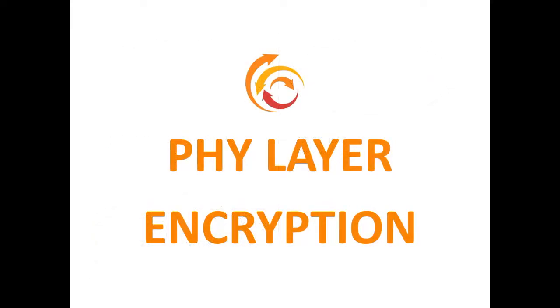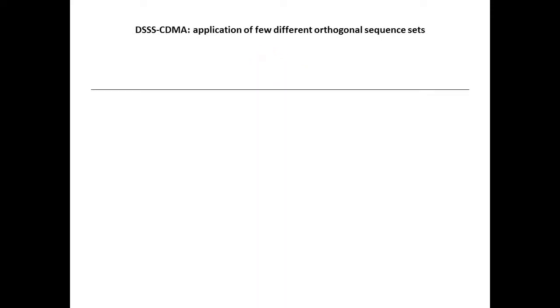The company's physical layer encryption technique belongs to the first type and is based on the direct sequence spread spectrum CDMA technique. Common DSSS CDMA uses Walsh, Gold, and Kasami codes for data transmission. Also, other modern complementary, zero correlation zone, or large area synchronous codes are considered for use in future CDMA systems.